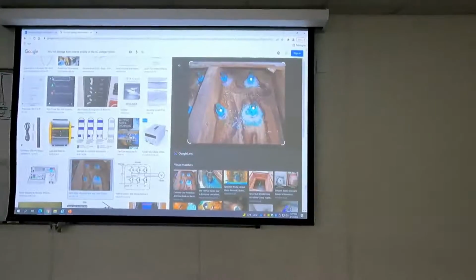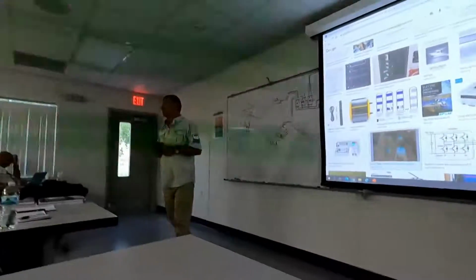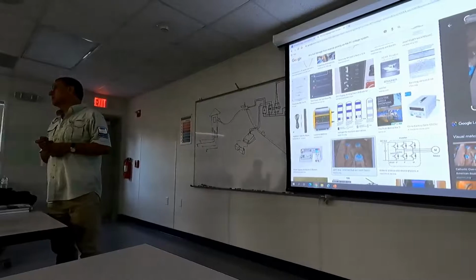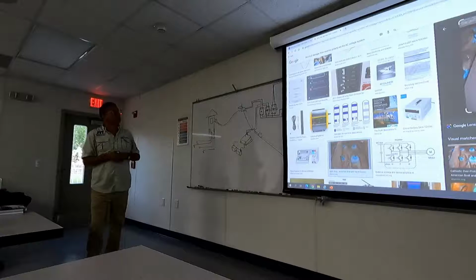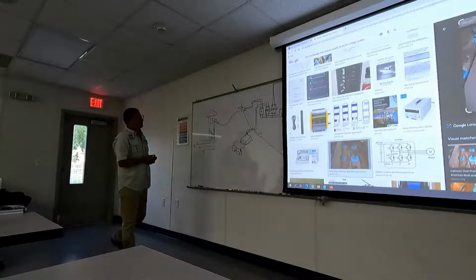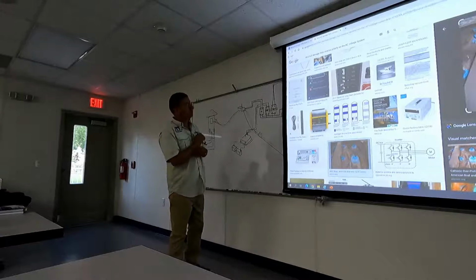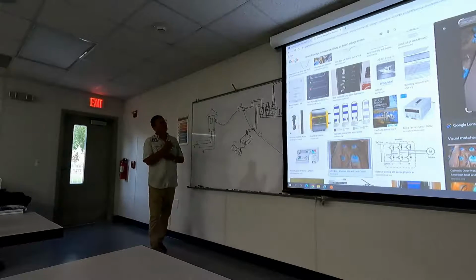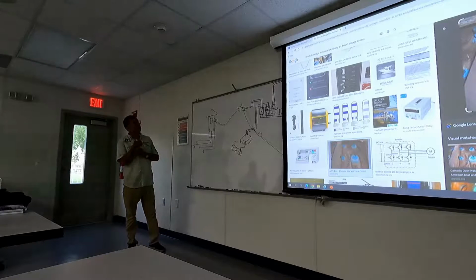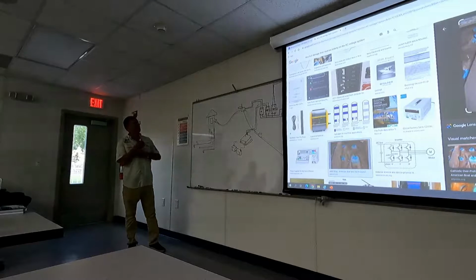How many times have you run into reverse polarity on boats? Reverse polarity is usually done by someone. It's not something that just happens. Someone was working on something. Sometimes it happens with just a short power cable. Whoever did the panels, when you make panels, you should make the wires long enough so that when you take the panel off, you can see it. Some people make them so short that you can only see so much, so it's very easy to make a mistake. That's why I like making my wires longer in the panels, even though I have to tuck the wire.